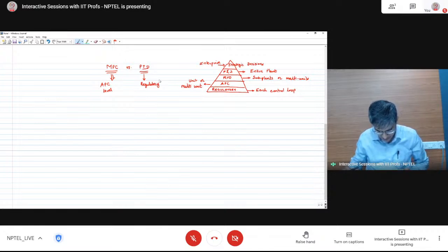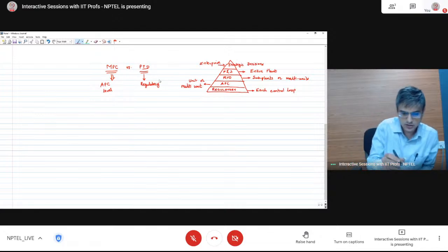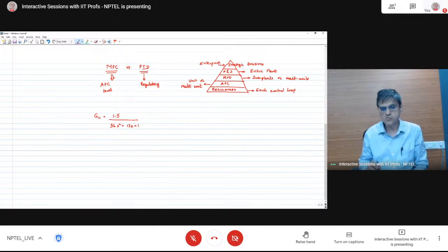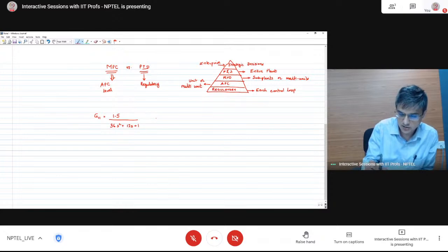Please explain the derivation of G11, G21, G22 for tutorial part 1 for the MIMO system. Okay, so let's say, again, I don't remember exactly what that was, but let's say this was e to the power minus 5s. There was no time delay. So let's see, divided by 36s squared plus 12s plus 1. Okay, so you can convert this into state space format.